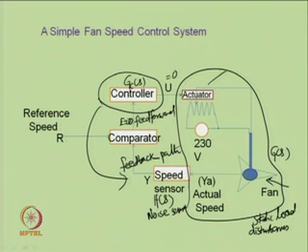When the fan has achieved the desired speed, at that time the controller may not act. Controller action is redundant. One does not require the controller in the loop when we are getting the desired speed from the fan, but the input to the fan is not disrupted. Rather, the control signal equals 0, therefore the actuator may not be acting, whereas the fan is in action and giving us the desired speed.